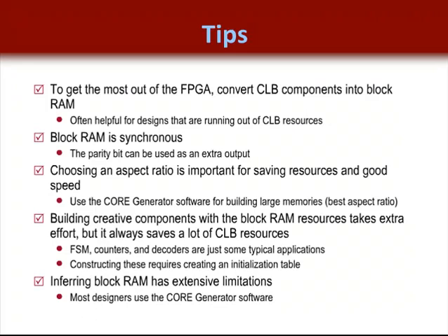As I mentioned, finite state machines, counters, and decoders are just some typical applications. Constructing these requires creating an initialization table, which, as I mentioned, is probably the biggest caveat. It's large and it takes a bit of time and effort. But if you've ever done microcoding, you probably won't have too much difficulty. And inferring block RAM has extensive limitations. Most designers like to use the core generator in this case.